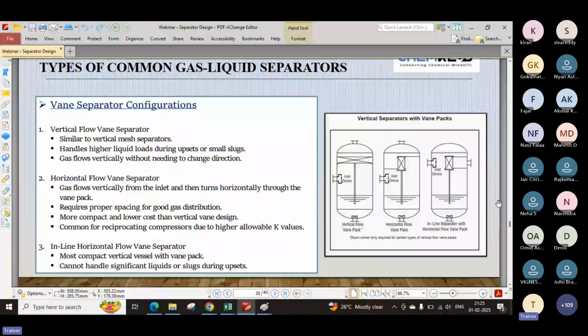Or you can see again the horizontal one, where gas is flowing through horizontal sections. But whenever we have any separating device in the system, there are three main zones. The one zone is where the separation is happening because of gravity. The next one is because of the forced media or external media available in the separator, which is there to enhance the separation. This is in the horizontal direction. This is again horizontal. In this one, the flow is happening in the vertical direction.